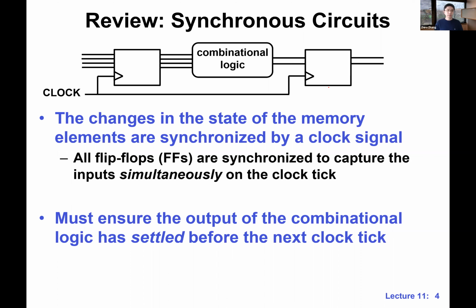The opposite of a synchronous system is something called an asynchronous circuit or asynchronous system. There's a short section in the book you can take a look at. With an asynchronous system, we do the communication using handshakes. We have a sender and a recipient. The sender will send a request and the recipient will send an acknowledgement. So we do this so-called local handshake to complete the data transfer.